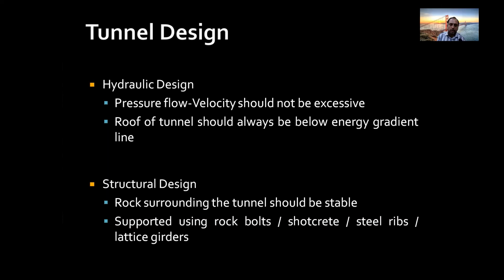The structural design means the rock surrounding the tunnel should be stable. It should not collapse, there should not be excessive dilation, there should not be excessive settlements, and so on. And this entire tunnel has to be supported by itself using rock bolts, shotcrete, grouting, steel ribs, lattice girders. These are technical terms that will be discussed in more advanced lectures. But yes, this entire tunnel should be stable.